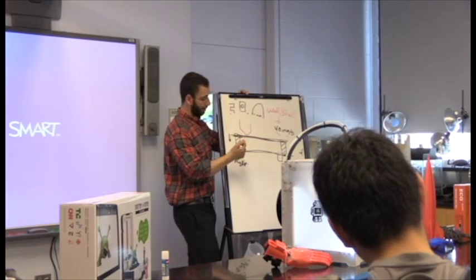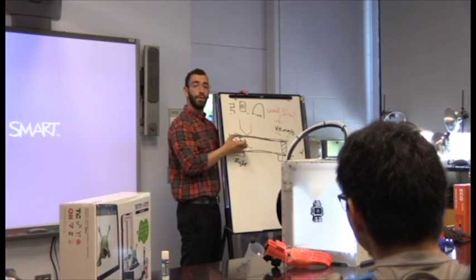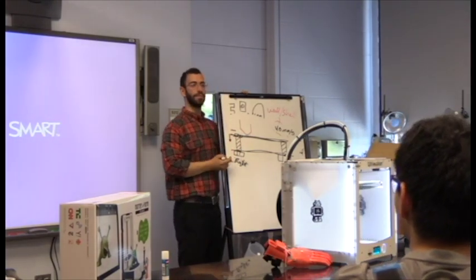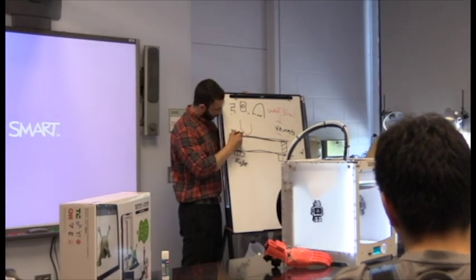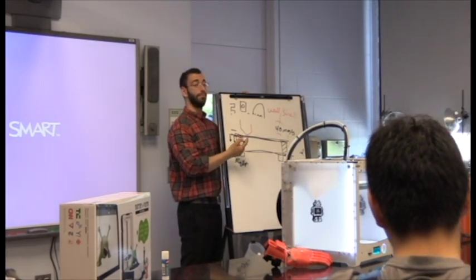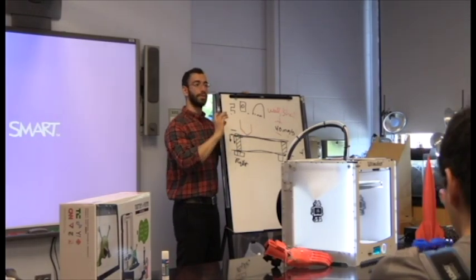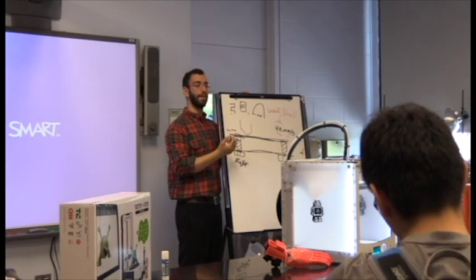As I go to the right, the screw's threading through, pulling down on the nut, increasing the space between the nozzle and the bed. Does that make sense? So as I go to the right, it's pulling the bed downwards, which is really increasing the space between the nozzle and the bed. So it's tighter and it's looser up here. So that's why righty-tighty kind of doesn't work.